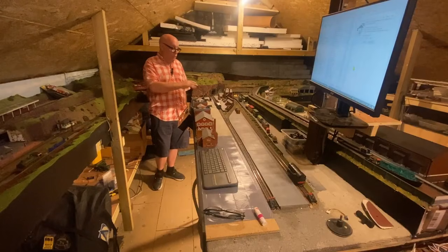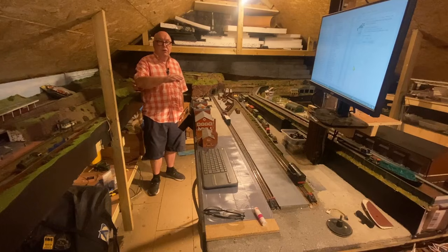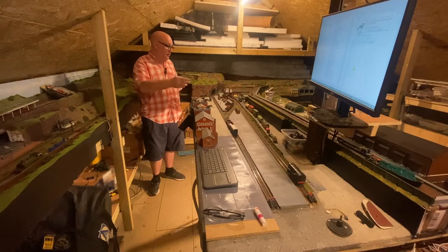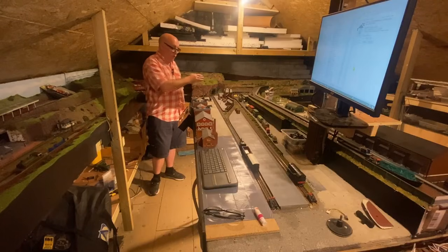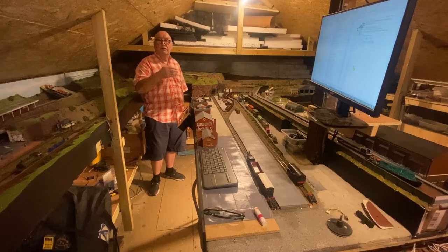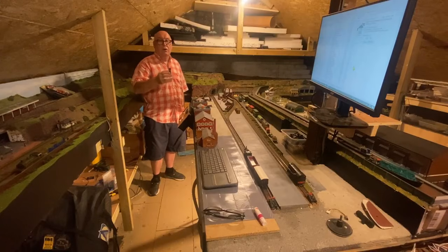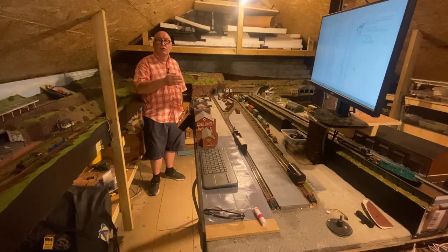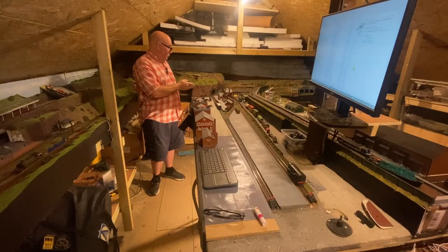Now, this could be done just using JMRI and scripting with timing. So you could time how long the train takes and then do it that way. But I'm actually doing it using 4 spot detectors which are underneath the track. They're feeding the signal back to JMRI. JMRI then tells DCC-EX, or my command station, to change the speed and direction of the loco. So now, as you can see here, it's moving along, it's sped up a little bit, slowed down, reached the